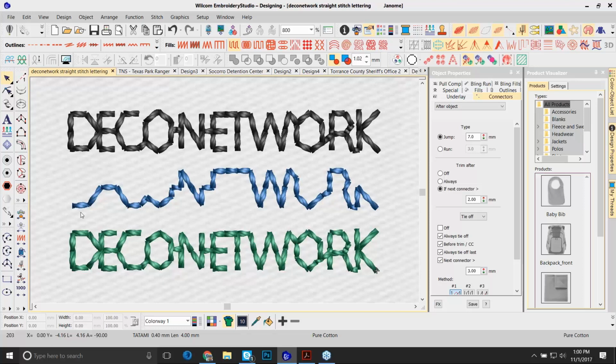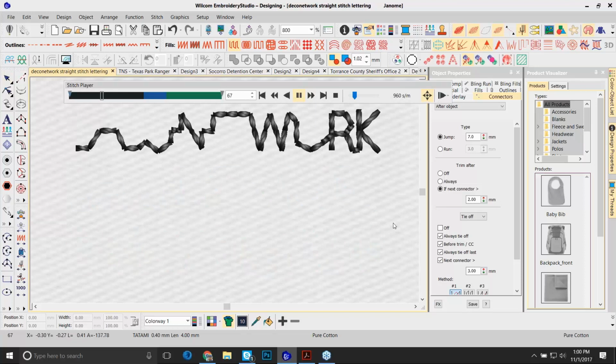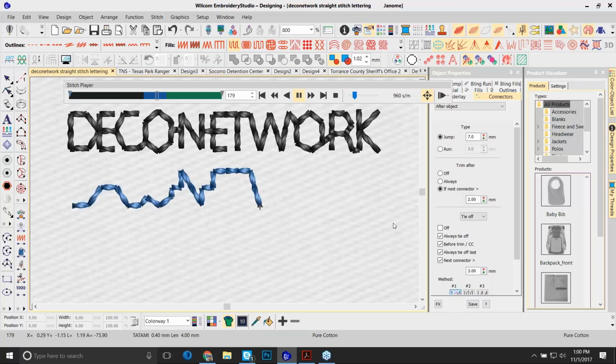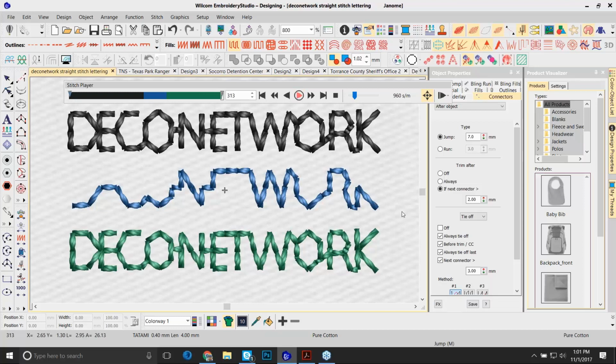They won't be obtrusive. But the first tour goes from left to the right in the most expedient fashion possible, and then the next tour goes back across, filling things back in as I go. Now I'm actually going to go ahead and rerun this for you so you can actually watch that work. As you can see, you can actually see each pass separated. Every spot is only ever covered twice, and that's going to give you a uniform thickness across.